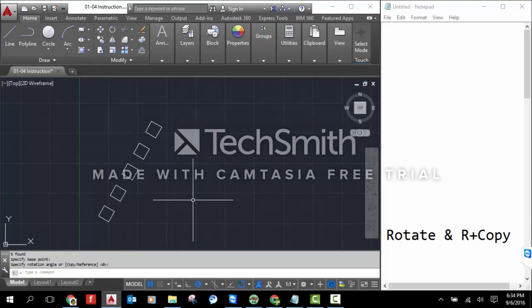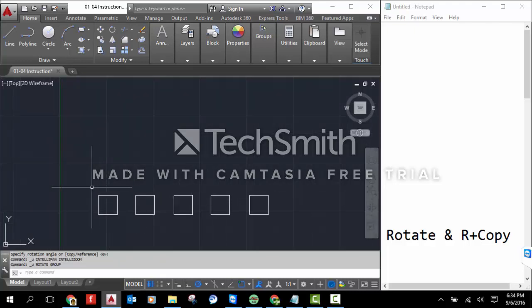Well, let's say I wanted to do rotate plus copy. So I'm going to undo that. Repeat the same steps. I'm going to select it first, or if you click rotate, it's going to say select objects. So you can select 1, 2, and once you're done selecting, press enter. Now I need to specify the base point. I'm going to do that same base point, the midpoint on the far left shape.